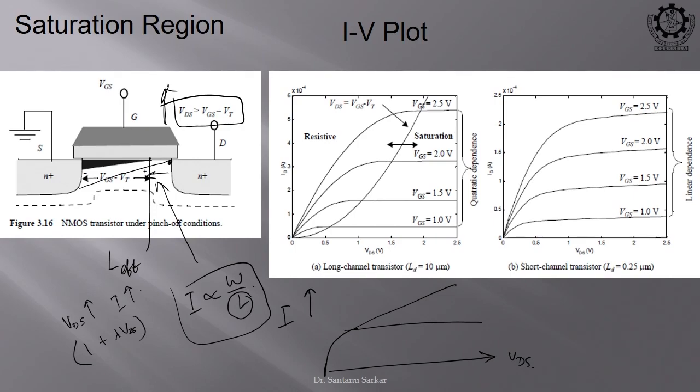Okay. So, this slope gives you a hint of the resistance. If you invert this, you will get the resistance. This is your del I, this is your del VD. So, if you invert this, you will get the r naught. Capital R on was the resistance at the linear region, and in this region your resistance is denoted by small r naught.